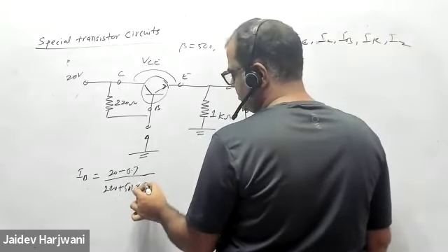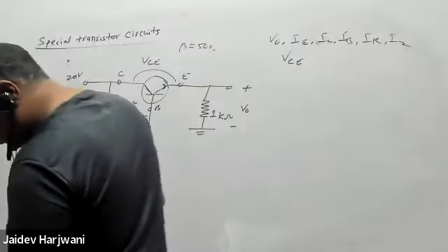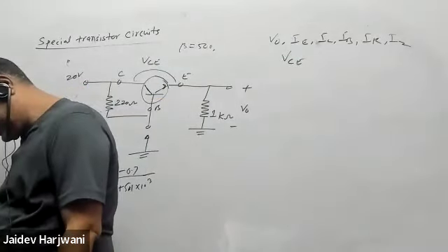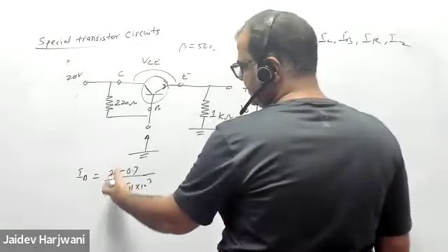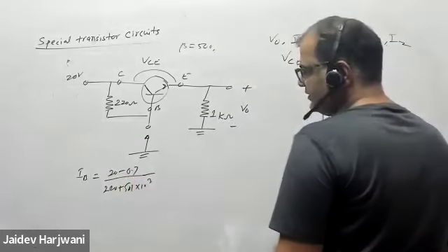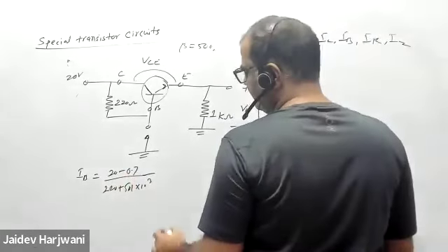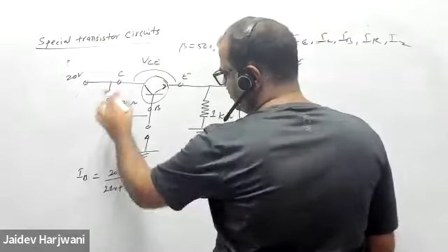kilo ohm. And this is 220 ohm or kilo ohm, only given. So we can almost neglect this, it is nothing, 0.2 kilo ohm. So you tell me how much IB is coming. Solve the IB and find the drop across this 220 ohm.